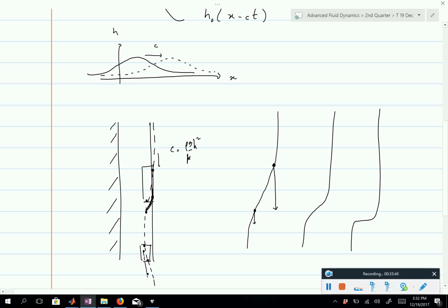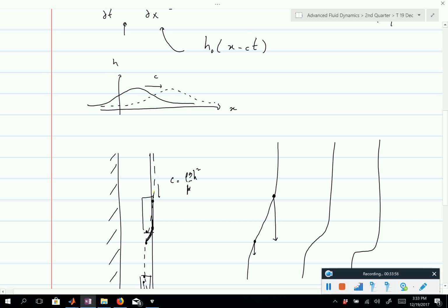So you cannot avoid those little droplets. They're going to happen. As your film flows, whenever you have a decreasing slope, when partial h over partial x is negative, the slope will tend to increase, and that will create an initial bulge in the paint. That bulge is going to destabilize in this direction, and then your little droplets form. So if you had to design a paint, you would design one which dries quicker than the characteristic time scale for this instability, or for that shock, to occur.